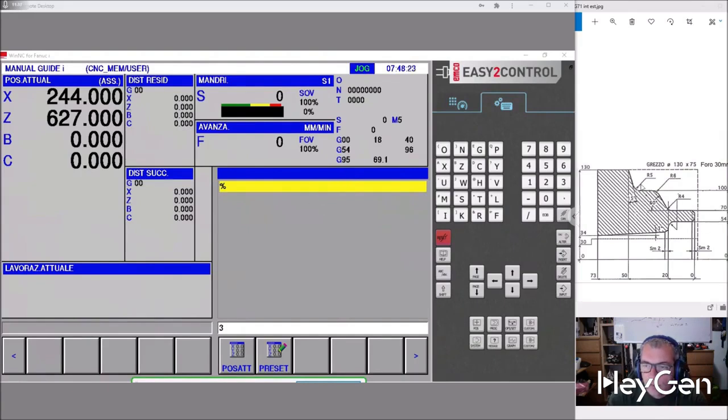I did on the whiteboard an example of how to profile a piece by starting with G42, which stands for tool radius compensation. However, without putting G40 at its end, which you must include when there's a G42, to cancel out and negate this tool radius compensation before one can go back to rapid movement mode again safely and securely. Well, now, the whiteboard doesn't give me any errors whatsoever. Indeed, there, you can do whatever your heart desires freely.